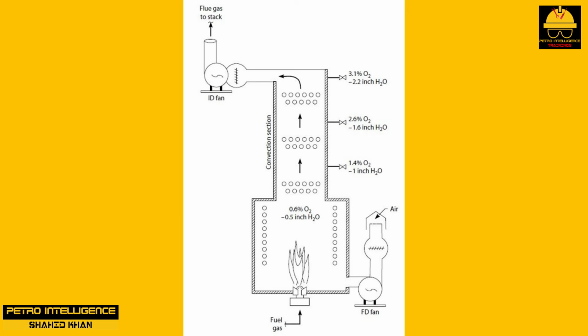The convective section, as shown in picture, is under negative pressure, so air leaks in and mixes with the hot unburned hydrocarbons, which then reignite. Thus, we have afterburn in the convective section. The heat of the fire in the convective section expands the flue gases, causing a positive pressure in the convective section, which stops the air leaks. After some period of time, the fire in the convective section has consumed all the tramp air and is extinguished.